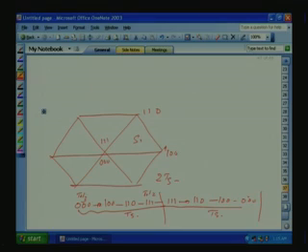So, for a 1 kilohertz switching, our TS has to be 500 microseconds. Then appropriately, we have to toggle a counter for the zero vectors and the switching sequence has to be changed. So, this way very easily we can implement the space vector PWM in the linear modulation. Okay. In the over modulation, that means when we want to go to the extra modulation range, there the zero period will be 0. So, whenever the zero period becomes negative, we adjust the gain such that T1 plus T2 is equal to Ts. Then you get the over modulation.